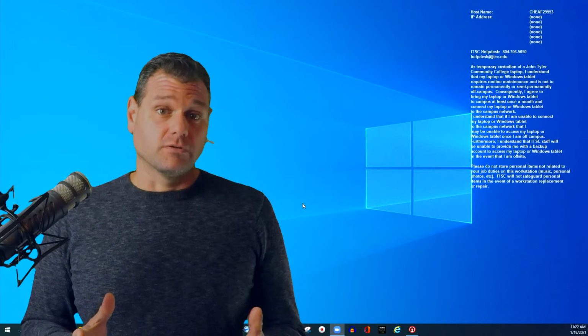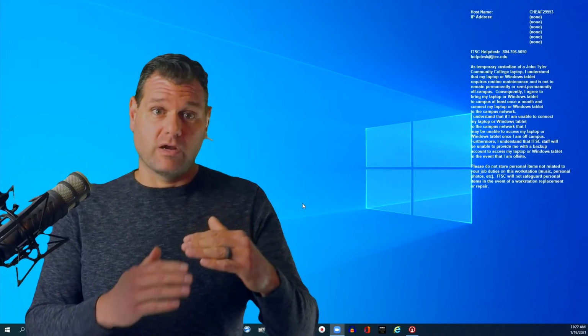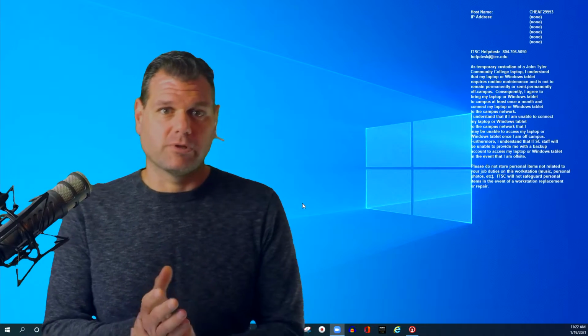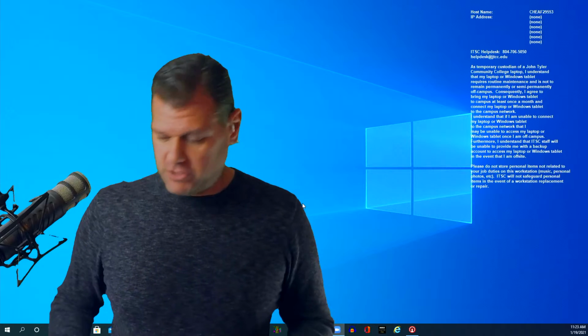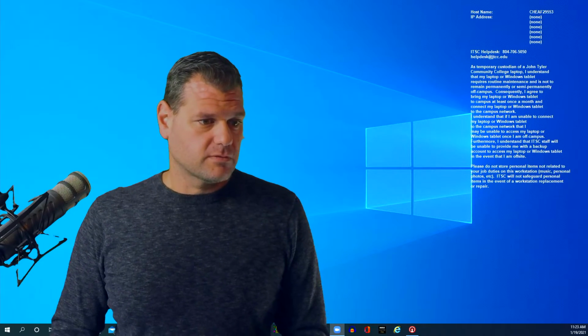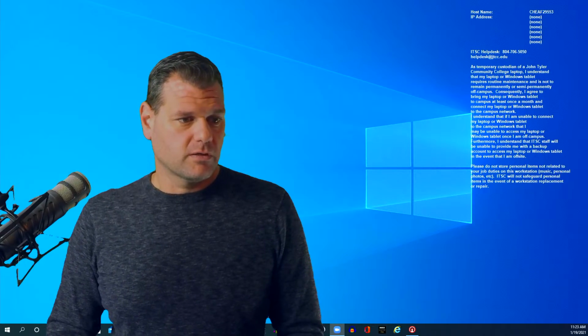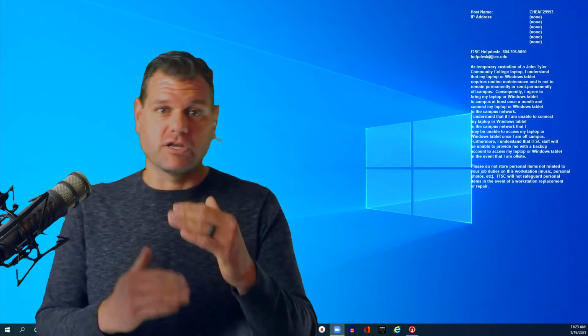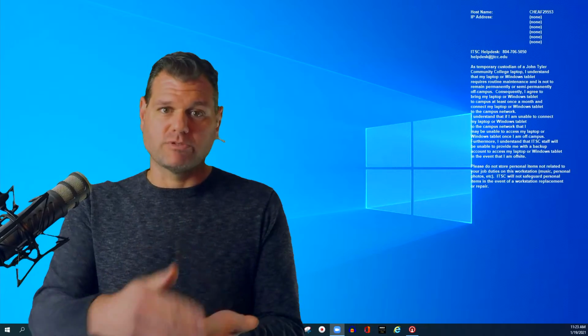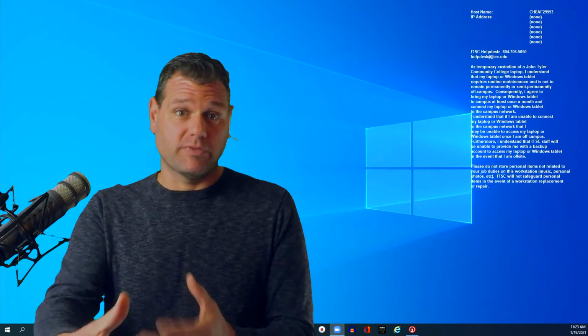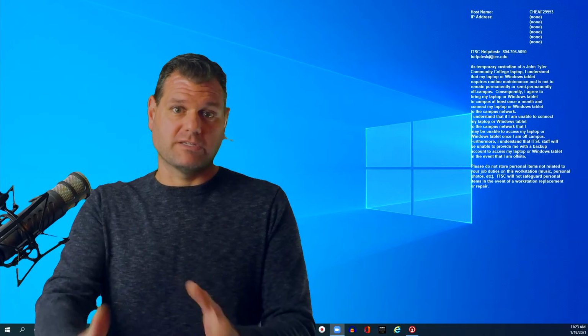Yes, if it's unconditional. You could have a condition on there. The reason they typically use these is when you want to turn off a section of logic that is, let's say, a fault. Let's say something happens and you have a set of pumps or motors running that is dangerous, something that is going to hurt somebody or mess a system up, right?